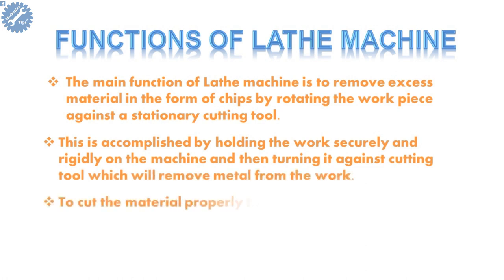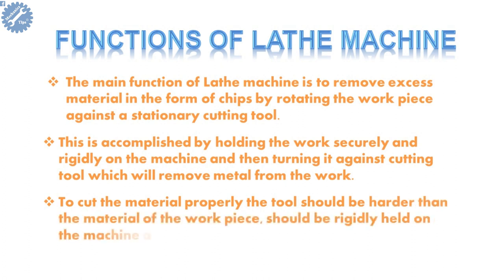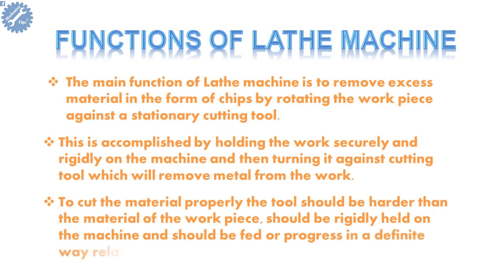To cut the material properly, the tool should be harder than the material of the workpiece, should be rigidly held on the machine, and should be fed or progressed in a definite way relative to the work.